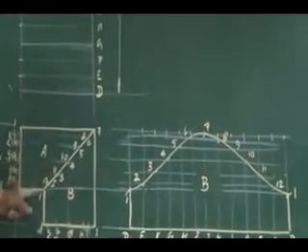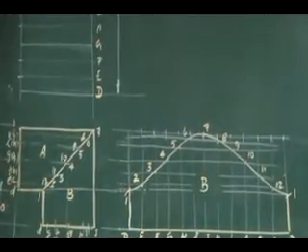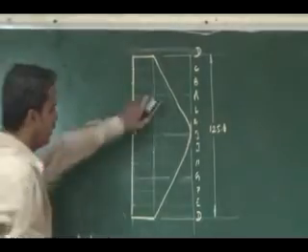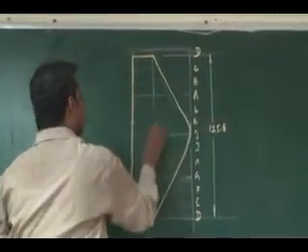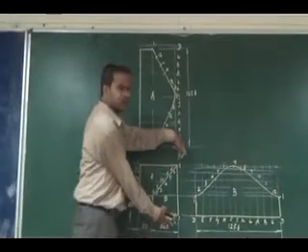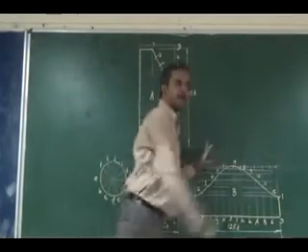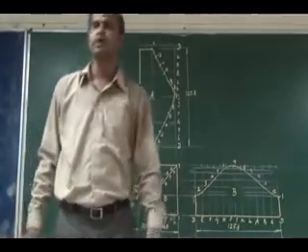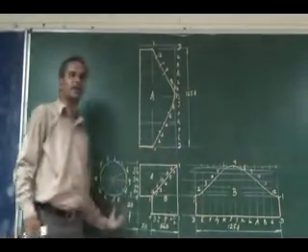Similarly, I will have a development portion for A also. Similar to that, I can project these cutting points. This is the development portion of A. Is it clear? If the height differs, the development will differ. It's similar to your previous chimney problem, so carefully mark the generator locations.